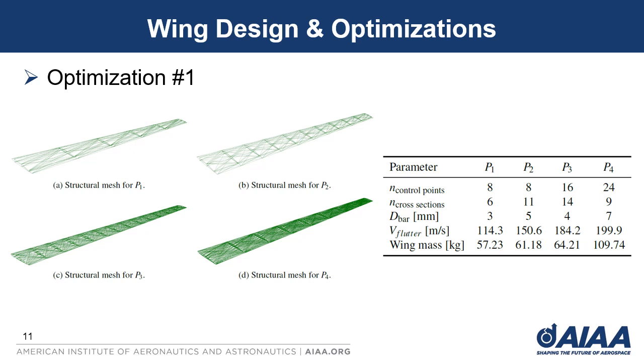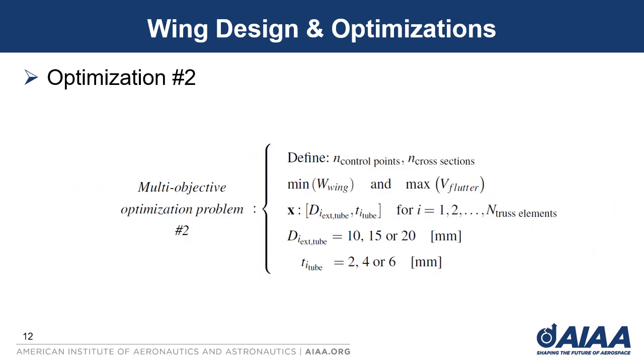The details of the wing optimization of the 4 points selected are displayed in this table. In optimization 1, we can see that it's not very efficient to consider all the modular structures as solid bars. Therefore, at this point, the objective is to optimize all the modular elements individually. In other words, the optimization will try to eliminate some elements and will check how the resultant weight and elastic behavior are. The optimizer will design the wing eliminating or not the lattice elements.